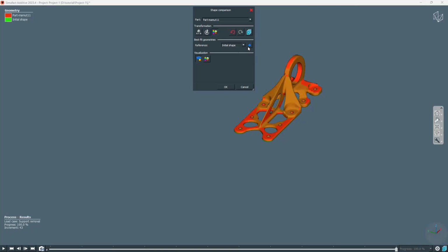Okay. So why do we do this? We are trying to see the deviation of your CAD model from the printed part. Okay, so what will happen is after manufacturing, there will be a surface deviation due to different effects. The geometry will not be as per your initial design. There will be a deviation. Okay, so we want to know how much is the deviation.